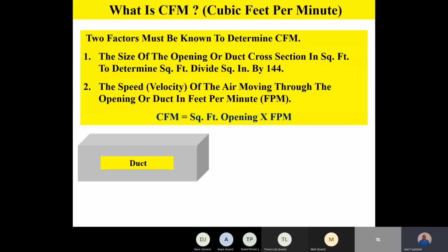Unless you have a local requirement that supersedes Manual D, we recommend you always design your duct systems with these factors in mind, because Manual D is the standard with which we design our duct systems in the industry. So for registers, grills, and diffusers, 500 feet a minute is recommended on the supply, and 400 on the return for those components. Any questions or comments so far?